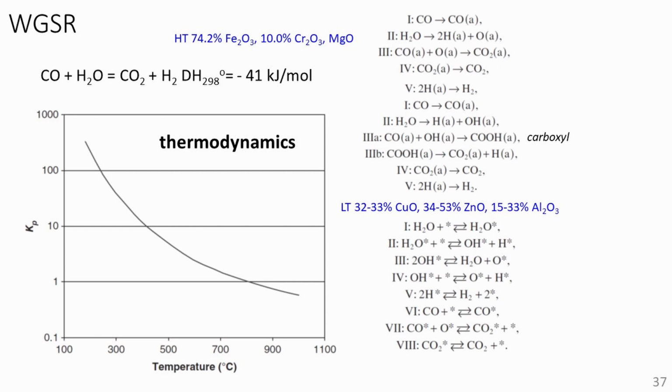The low temperature water gas shift operates in the temperature range of 200-250 and favors an equilibrium toward hydrogen. A shift carbon monoxide outlet concentration of 0.1 volume percent can be obtained. The water gas shift reaction utilizes fixed beds, typically with iron-based catalyst in the high temperature and copper-based catalyst in the low temperature water gas shift reaction.